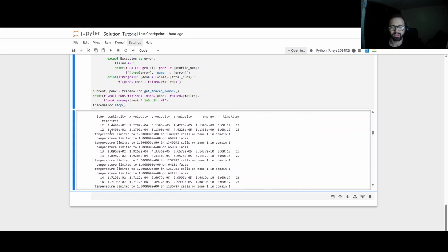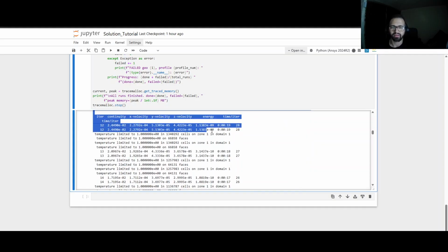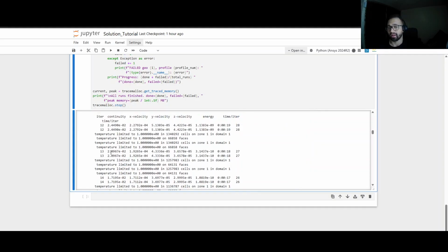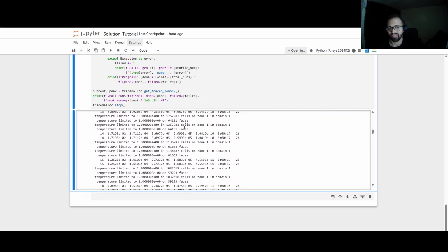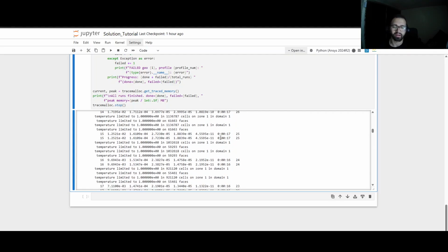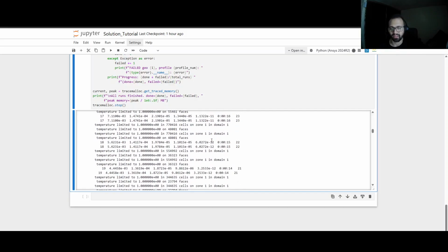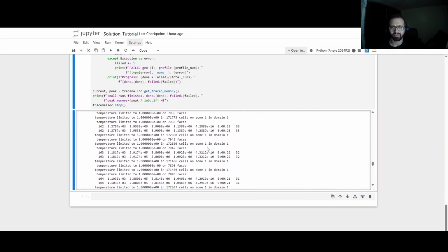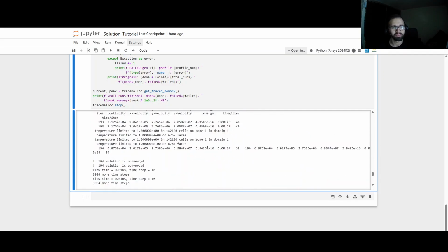And just need to make sure the residuals make sense while running. If you find these velocities are zeros or not changing, that mostly means either the velocity profile or the concentration one is not being read or assigned correctly. And just leave it. You can run it on your cluster and so on.